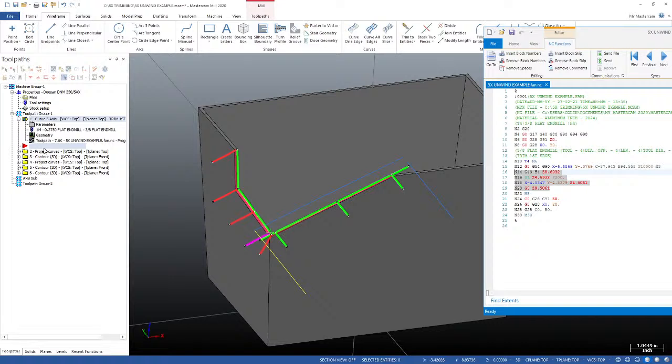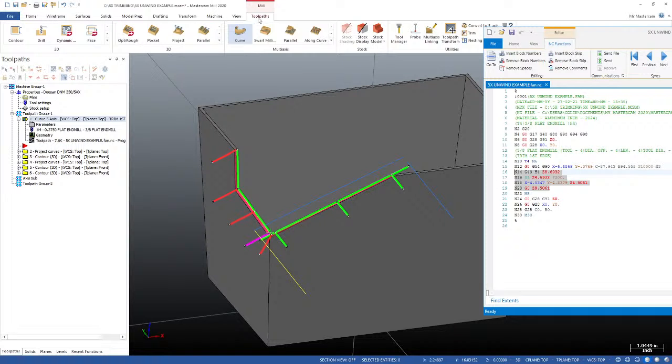So I'm going to do another curve 5-axis toolpath. So we'll do curve. I'm going to grab my 3/8 flat end mill for the second wall. I'm going to go in and edit this tool. I know you can't see this, but I'm just editing it real quick to change the RPM and the feed.